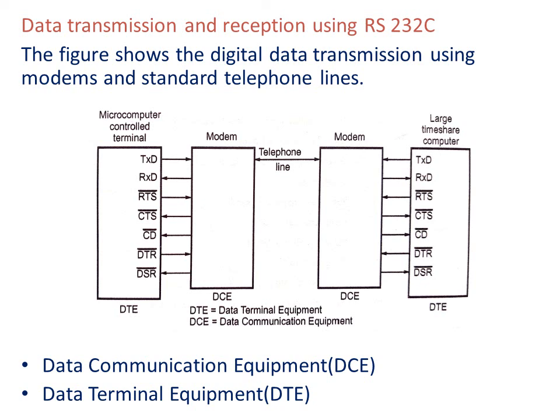After receiving DSR bar, the DTE requests use of the data channel by asserting the RTS bar signal to begin transmission. The modem at the receiving end is then dialed. This answer mode modem responds with a 2225 Hz carrier frequency.